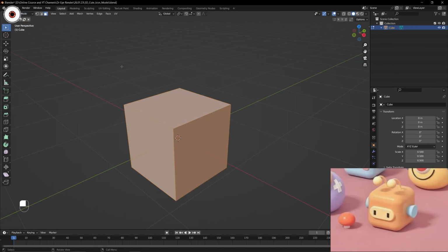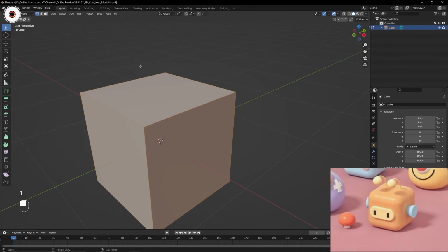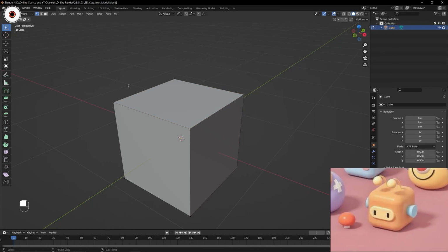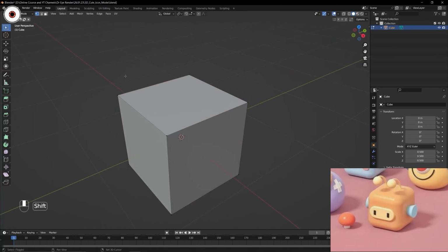So in here we have vertices. To select the edges, you need to go to edge mode. To select the vertices, you need to go to vertex mode. These are the vertices which I am selecting right now, and the combination of these 4 vertices makes a face. How do I know it is making a face?